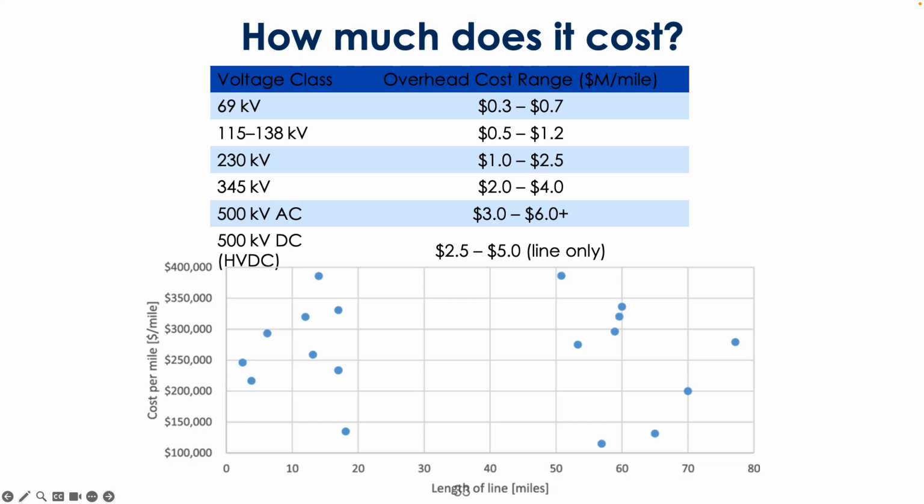And some of that high voltage stuff can be several times more expensive. So you do really want to think carefully about the constraints of your system and what is the most economic to build out, right? Typically the economics make the most sense to only move up to higher voltages as you transfer larger distances, because that's when the power losses are going to scale up. Okay?